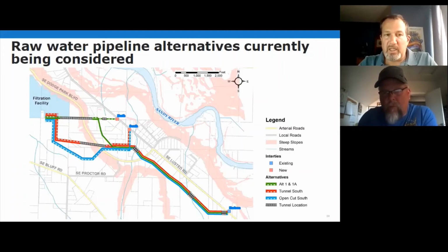We're also looking at some piles going up each side of that trench to be able to dig. That would be about a 30-foot wide trench, and you'd have to have room on the side of it to get stuff up and down it. So there would be a swath about 80 feet wide cleared up the slope. And we'd have to have an easement about 110 or 120 feet wide to do some tiebacks that would be under the surface beyond that 80 feet. And I take it with mixing of soils, you're talking about a trade name like quicklime or something like that to help stabilize the soil in that area, right? Yep. Okay.